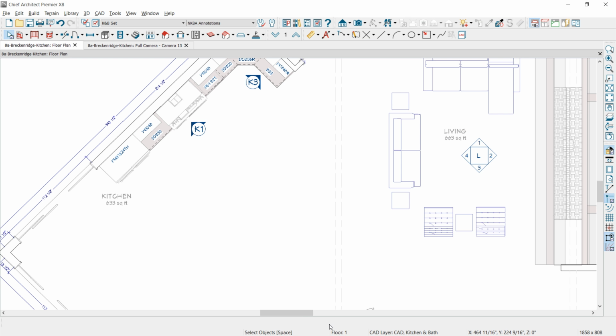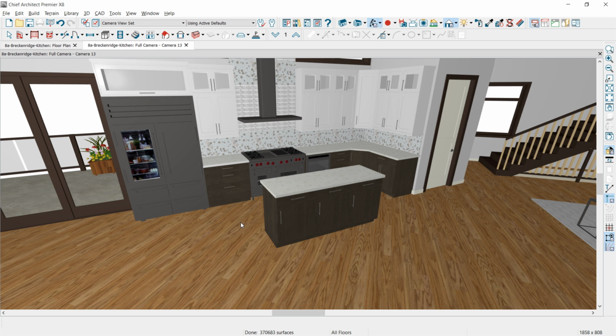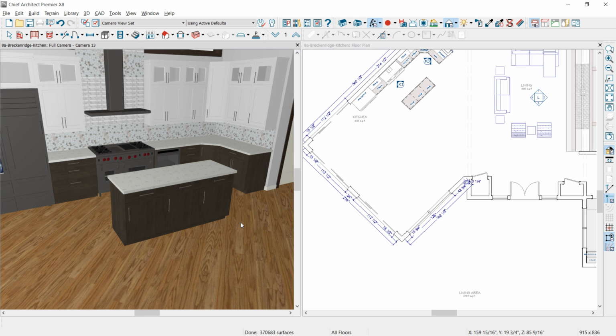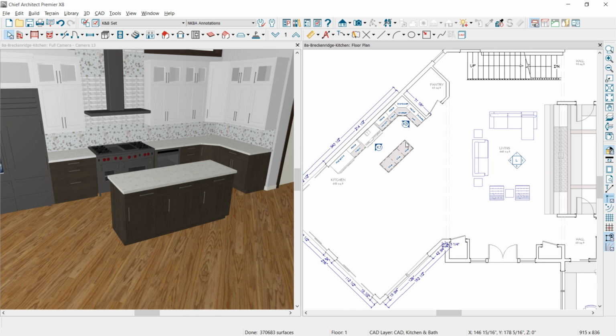To begin, I'm going to use the base cabinet tool and place 3 different base cabinets just out in this area, and I'm actually going to build the island in reverse order so you can see exactly the way it's going to look, and then we'll rotate it. If I press F7 and toggle to the 3D view, you can see our cabinets that are facing us. And I'm just going to press Shift F6 on the keyboard and do a little bit of design work.